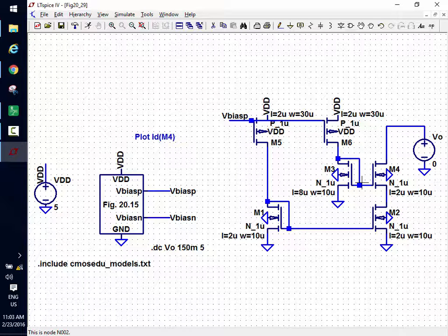So if I increase the length, what happens to the pressure drop? If I make it 100 feet long versus 50 feet long, what happens to the pressure drop from one side to the other? Yeah, it increases with length. So if I keep the same current flowing in here, but I increase this length, what happens to the pressure drop? Goes up, right? So I expect this voltage to go up. Before I had 2 VGS, now I'm going to have VGS plus a VDS sat. I'm going to go over this again when we meet.